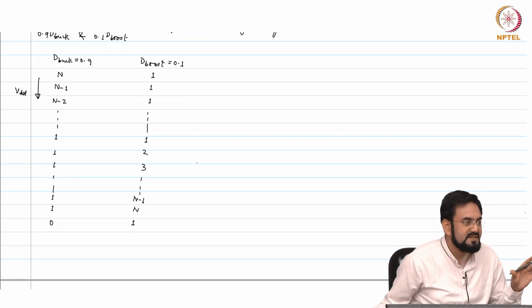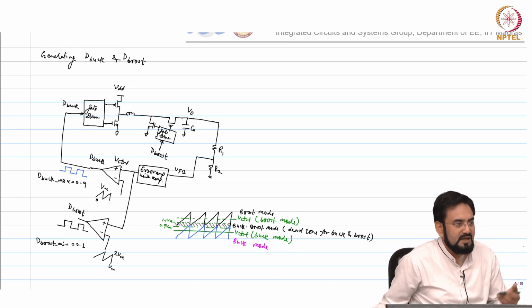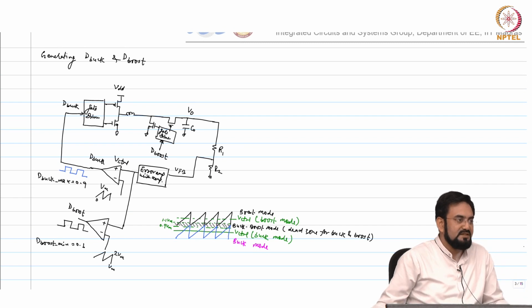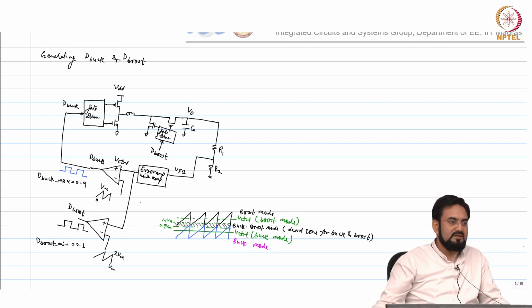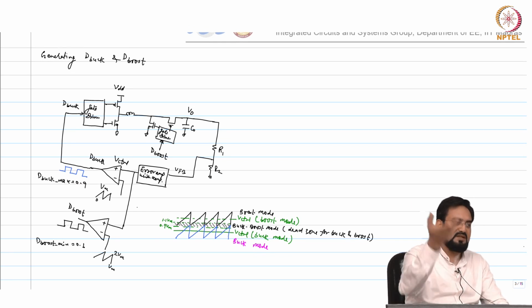You guys know ADC, flash ADC, it's just comparators. So take this V control, and you require multiple references here, and compare with that, and it will give you the code. Okay. So for 3-bit flash, how many comparators do you require? 7. For 4-bit, 15. But it is not necessary to use flash, you can use SAR or anything. SAR is even much simpler. It does not require that many comparators. And it is more digital actually, SAR.